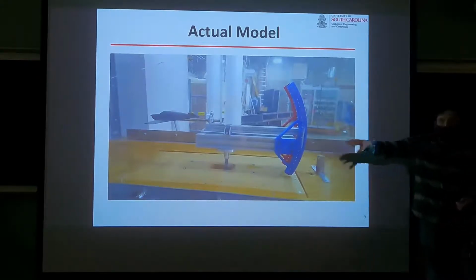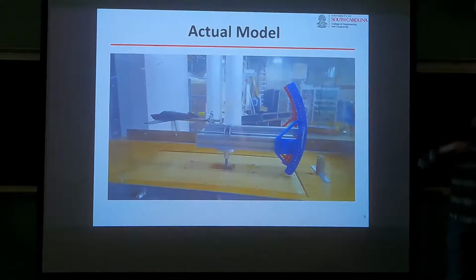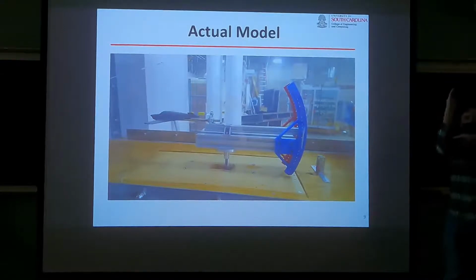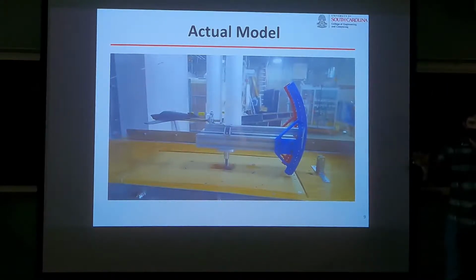It would have been more ideal if we could have changed this whole bottom plate that I was talking about that vibrates up and down. The way the load cell is set up on it isn't great either, because you're essentially counting on the deflection of that rod. It's a tension gauge, and the rod just deflects and pulls on that gauge. So it's not the greatest method of trying to find that drag.